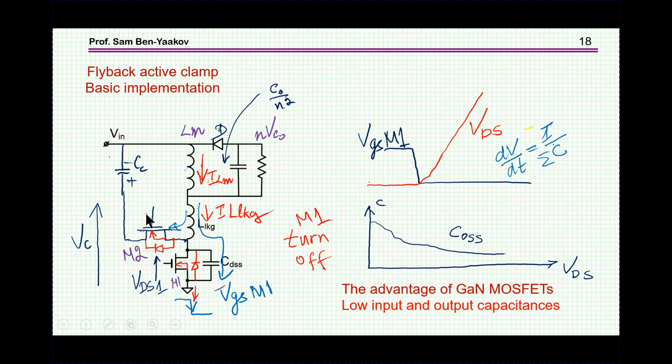Now, we don't want these capacitances to be very large, because if they are, then we are going to have a problem when we are moving back to the zero voltage switching, that is when the voltage here is dropping down, because we'll have to move energy back to this capacitor, so we'll need enough reverse energy in this inductance to charge these capacitors.